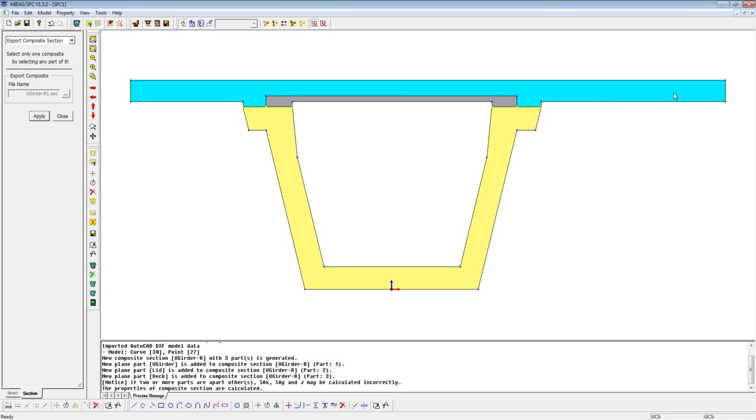So Abul, I would suggest you not to use rigid links. Instead, just use the dummy members, let's not call them dummy members, I'll call them transverse elements, with the cross-sectional properties of the deck slab, or based on Hambly's equation, if you are working on several cell box girders, then that is very useful.